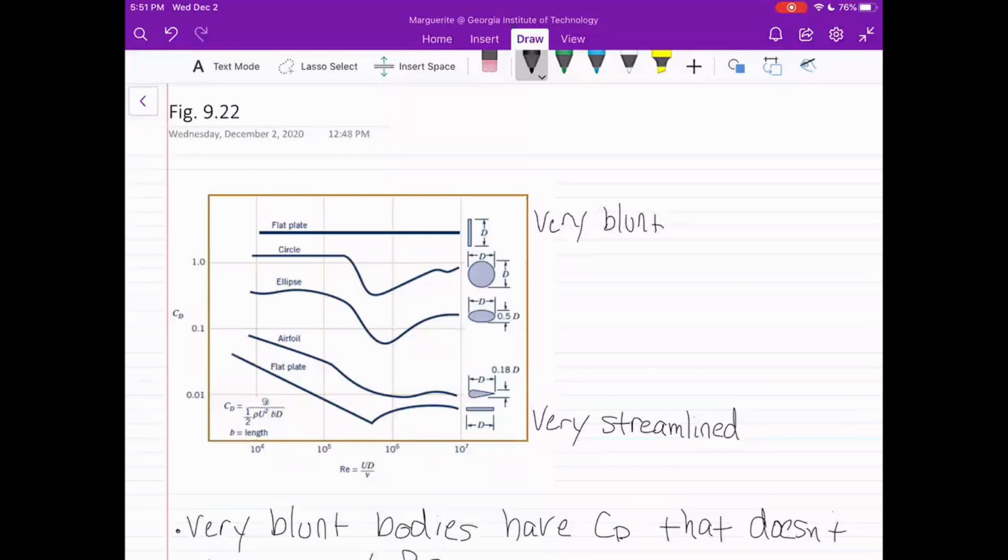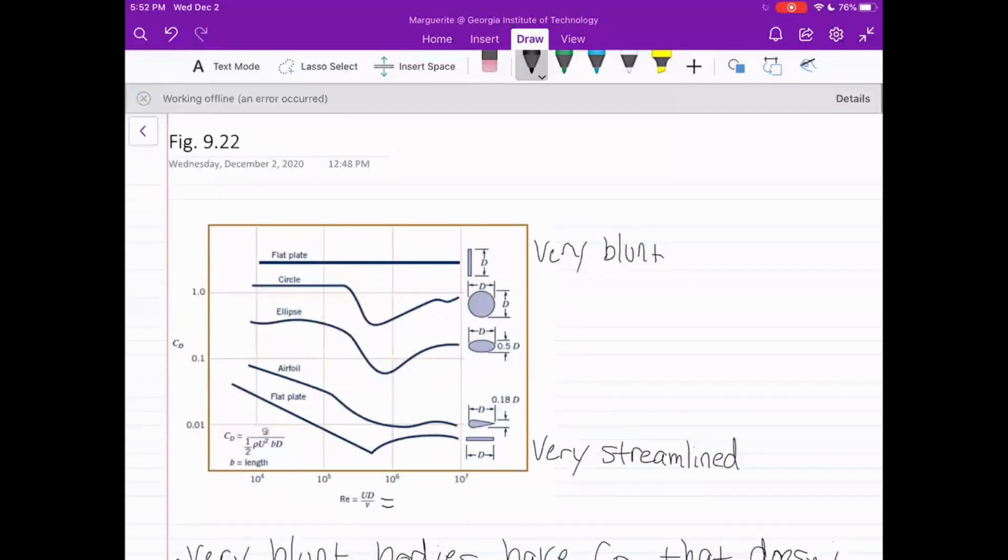All right, in the interest of time, I'm going to go ahead and share the correct answer. It actually is that CD doesn't change very significantly. It's a little bit confusing, but if we look at this, the Reynolds number is UD over nu, the kinematic viscosity. If our velocity doubles, then Reynolds number 2 is twice our original Reynolds number.